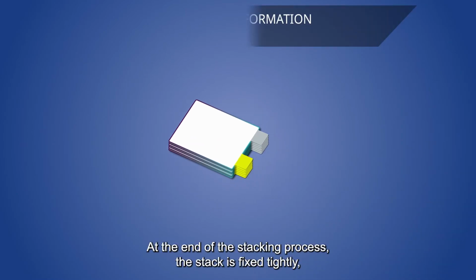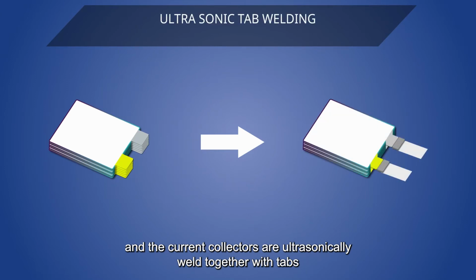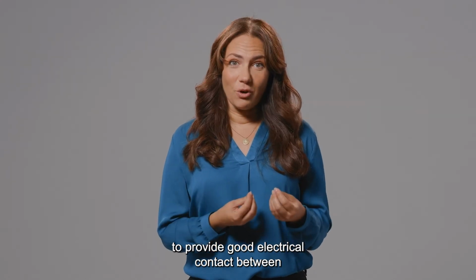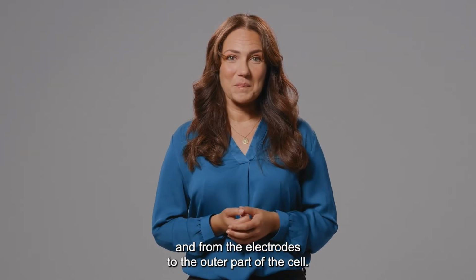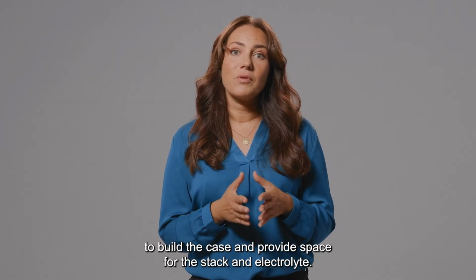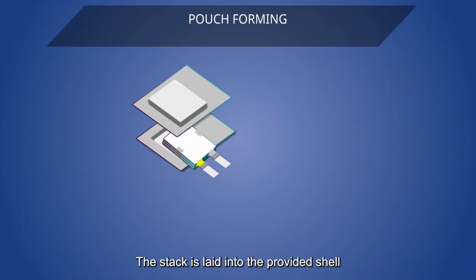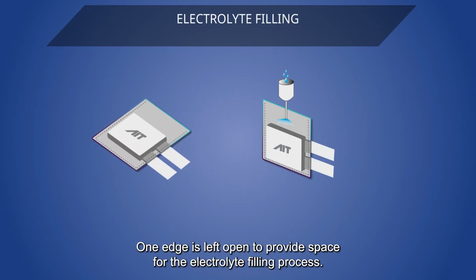At the end of the stacking process, the stack is fixed tightly and the current collectors are ultrasonically welded together with tabs to provide good electrical contact between and from the electrodes to the outer part of the cell. In the meanwhile, the outer shell, the pouch foil, is deep drawn to build the case and provide space for the stack and electrolyte. The stack is laid into the provided shell and sealed on three edges. One edge is left open to provide space for the electrolyte filling process.